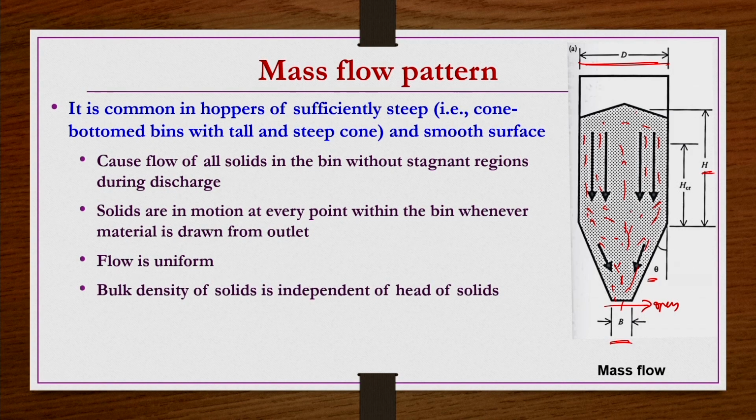And then, in general, the bulk density of solids is dependent on the head of the solids. But if you have a mass flow pattern in the bins, then it is possible that the bulk density may be independent of the head of the solids. Head of the solids is whatever the H is, that is the head of the solids. So if you have a mass flow pattern, the bulk density might not depend on this H.